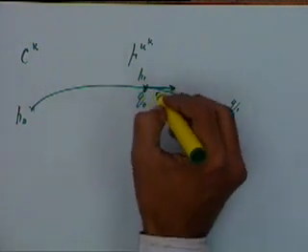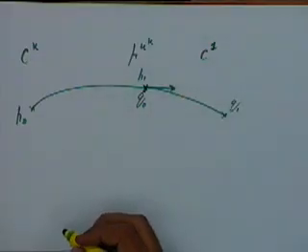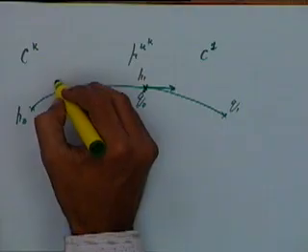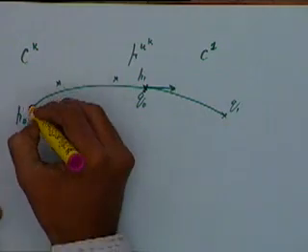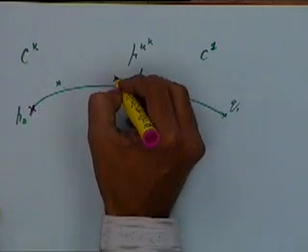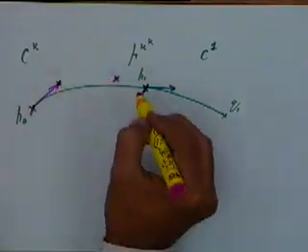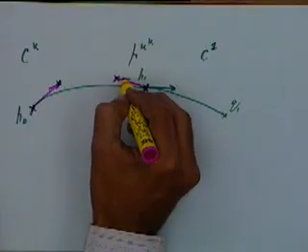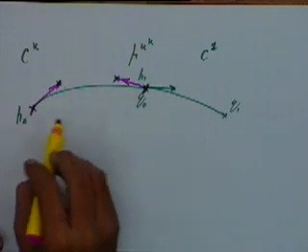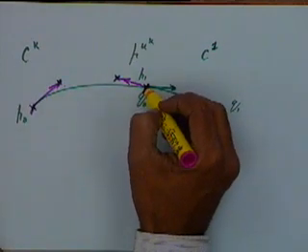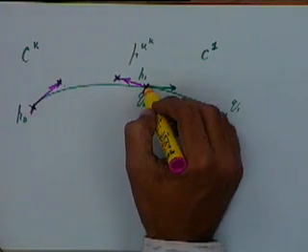And if I have two curves which have the same tangent vector, let us say this curve is defined through these 4 points, this point, and these two are giving the slopes. That means this is the slope at this point and this is the slope here. Now if I want to ensure C1 continuity at this point, even if I change P0, my C1 continuity at this point is going to remain unchanged.